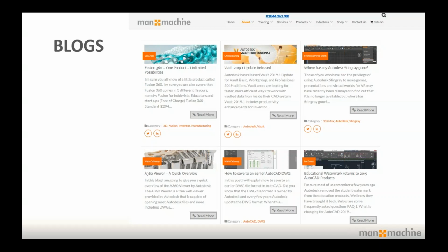Welded structures have a whole lot of challenges when it comes to simulating them. You've got porosity in the weld, you've got increase in stiffness, you've got changing material properties. And so lots of it comes down to experience, rules of thumb, and just being diligent with how you interpret the results. At the end of the day, it's a calculator, and it'll be silly in, silly out.